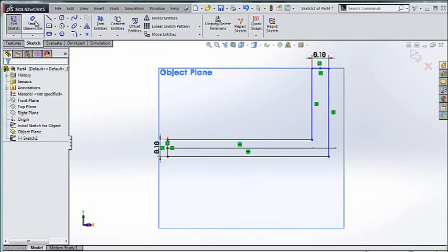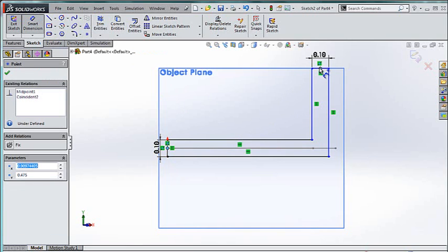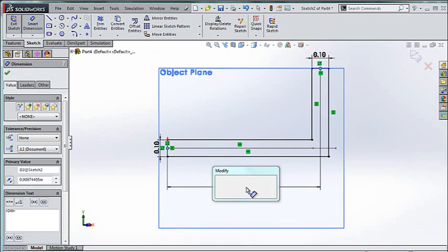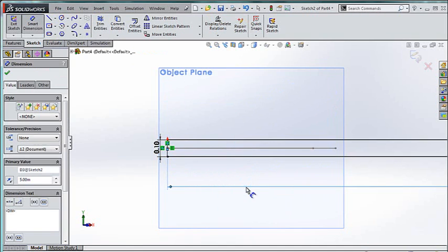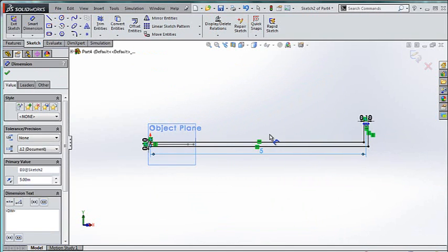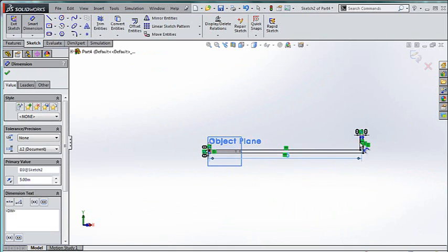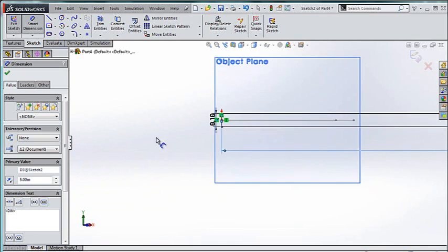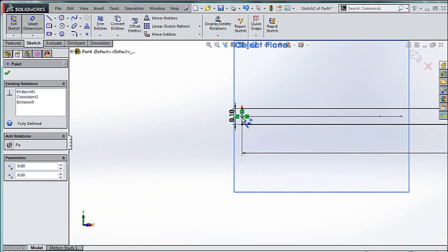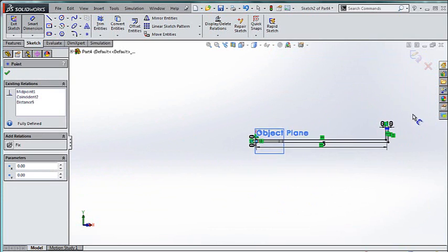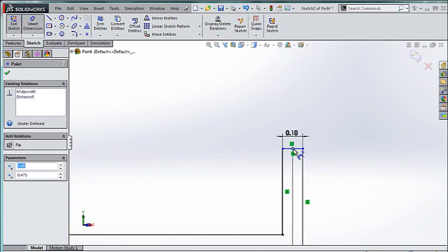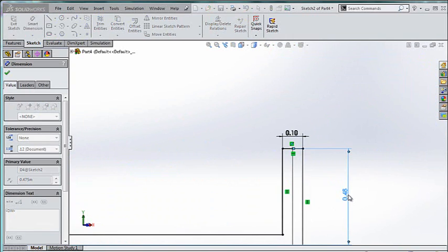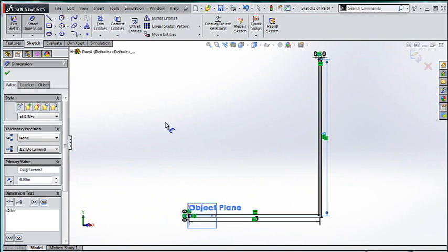And then I'm going to go ahead and make the rest of my dimensions. So I'm going to say from this midpoint to this midpoint in this direction is actually 5 meters. Hit F again to recenter it. Okay. Then I'm going to hit this midpoint again, and scroll out. This midpoint to this midpoint is 6. Hit F again to get it in the right place. Okay, so now that's actually my beautiful picture.